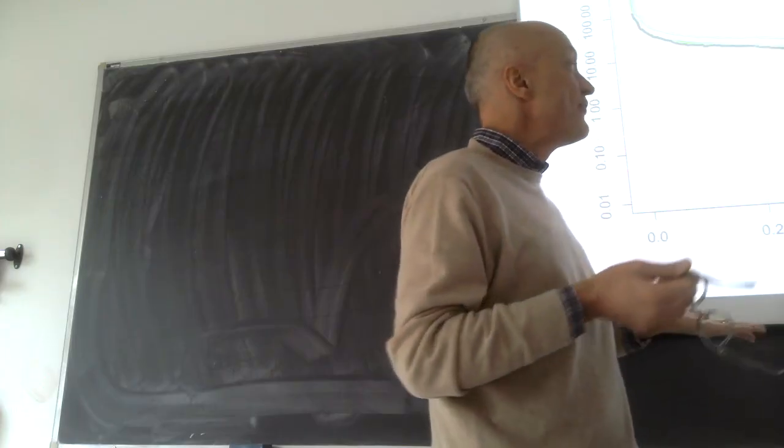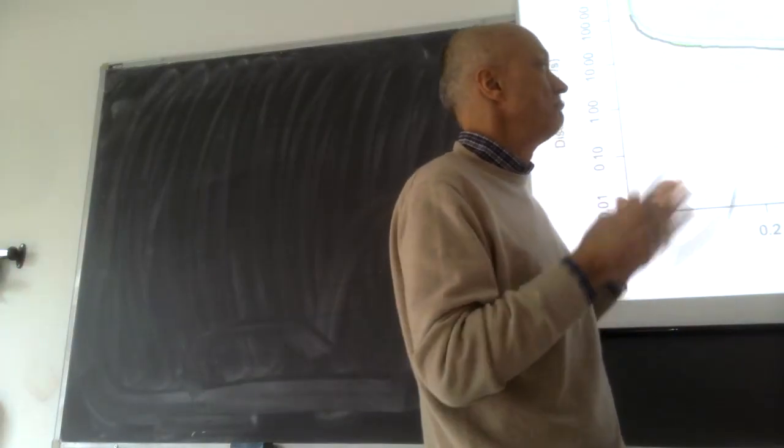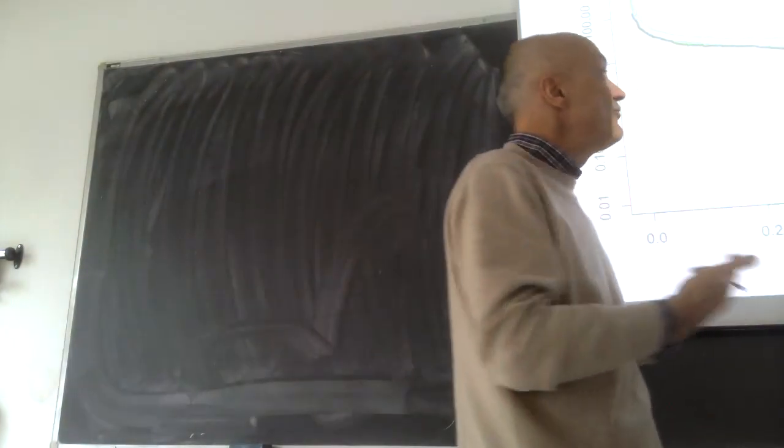But on the long run, 15 years consequently, you may see a big drop which depends only on a few very dry years in the sample. Sufficiently clear? Okay? Good. So if you want to depict and represent what's going on in an average or typical year, you look at the black line. If you want to see the real stream flow regime on the long term, 10 years or more, then you should refer to the period of record one. Good. Do you have questions on this part?